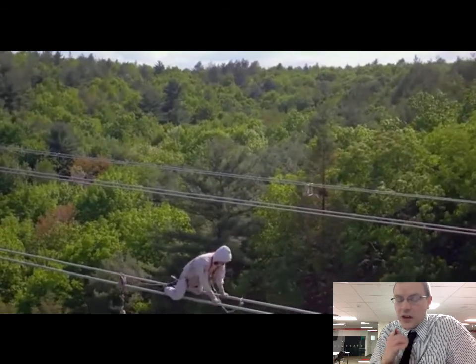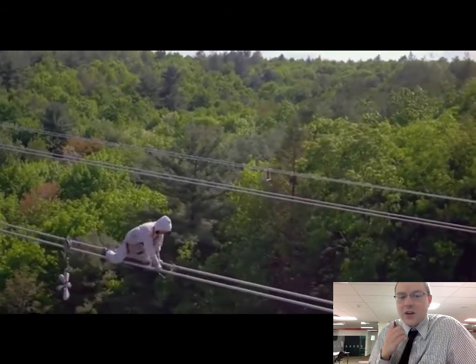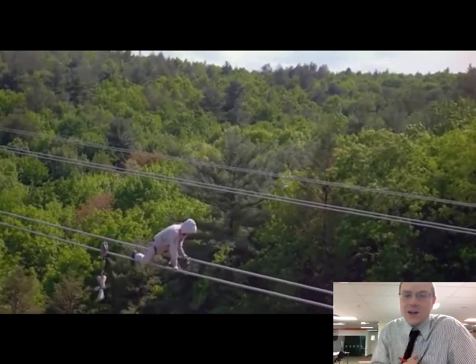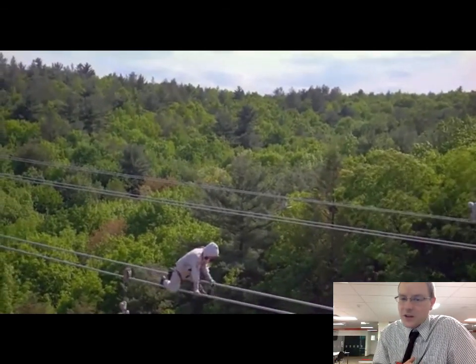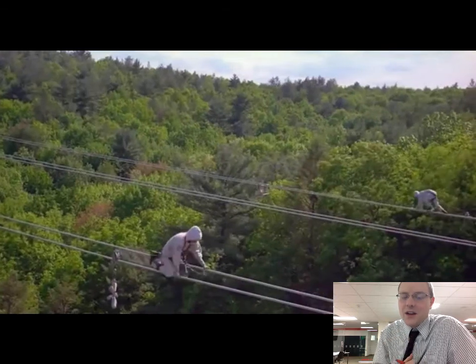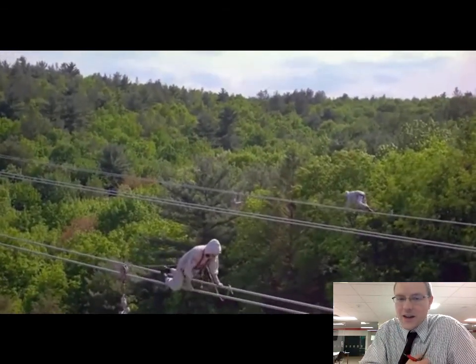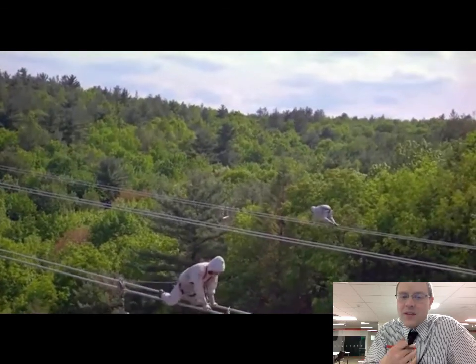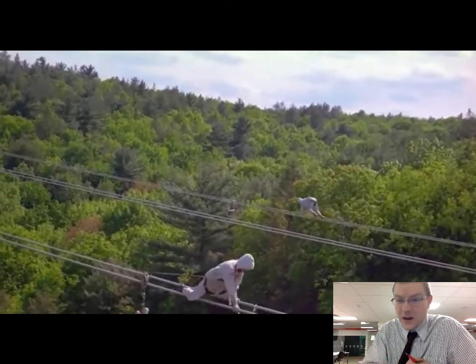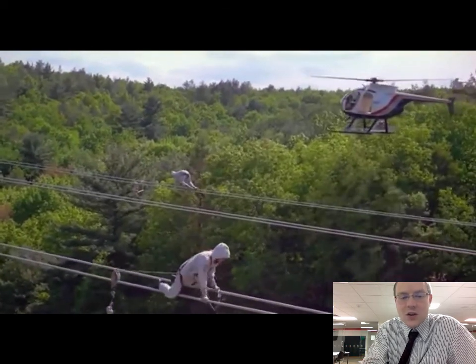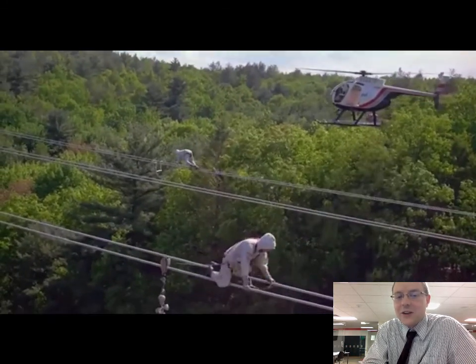He's raised up to whatever voltage that line is, but he's on an equal volt surface. If he reached out and touched the line across from him, where that other guy's working, then he'd have some problems. Or if he got to the very end and touched a grounding wire at that edge of that pole, then there would be a path from high to low volts. But you're perfectly fine to crawl on electrical wires if you're in a Faraday cage.